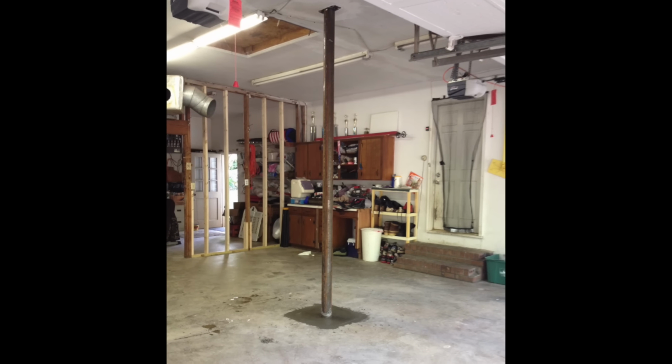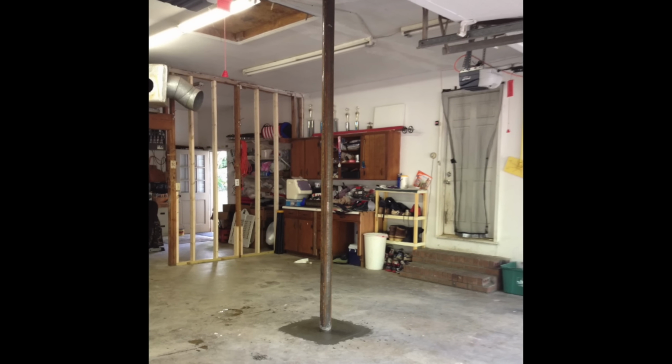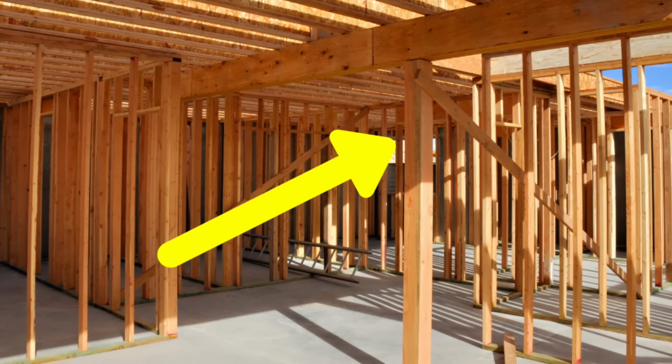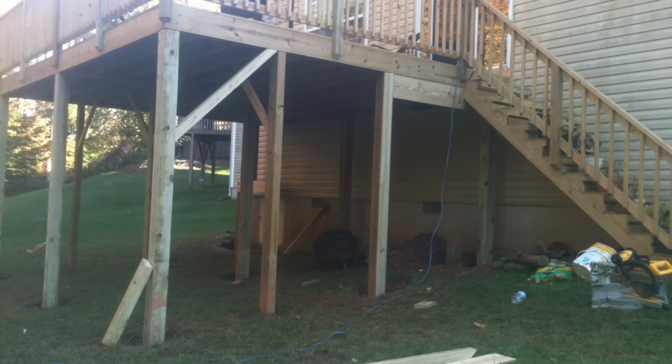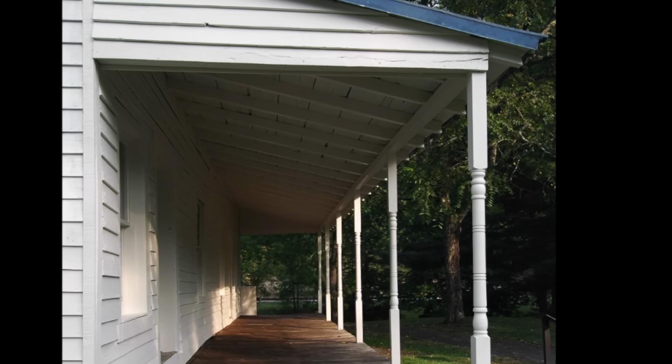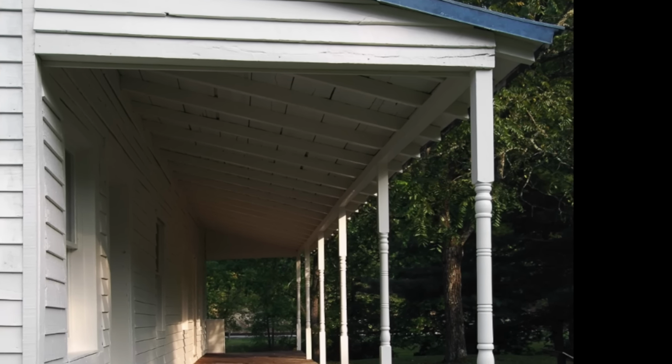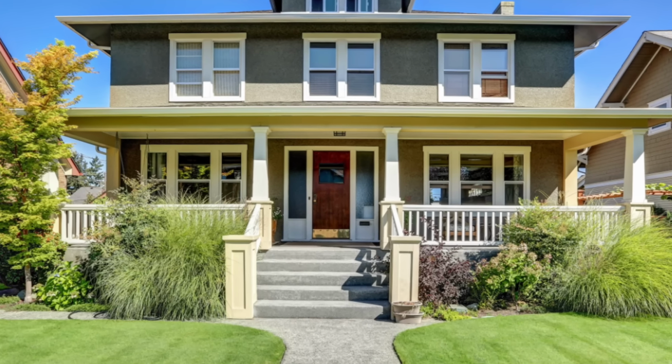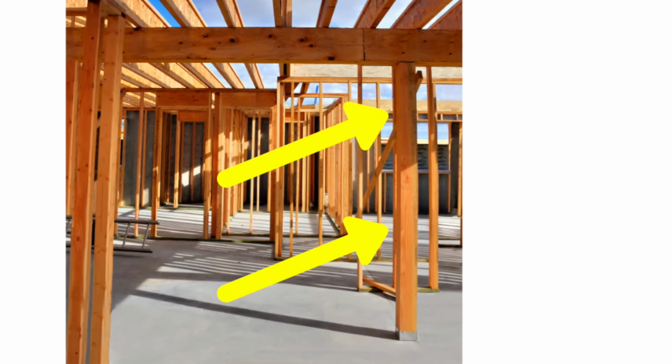These words, column, post, are sort of catch-all terms for a vertical support. Sometimes they're made of hollow steel, like this one I installed beneath an overspan girder in a garage. Other times they're made of wood, like the very common porch post. I installed these 6x6s beneath an under-supported deck. And on porches, you'll see wrapped columns holding up the beams that support the roof and ceiling. Sometimes these columns are very decorative, but they're still structural. But altogether, columns and posts transfer loads from a beam or girder down to somewhere lower in the foundation or another support.